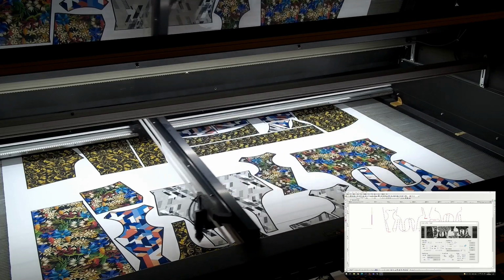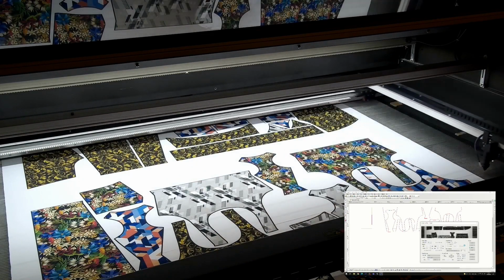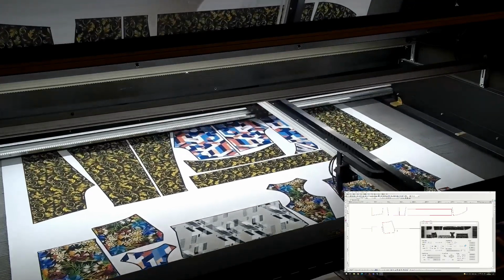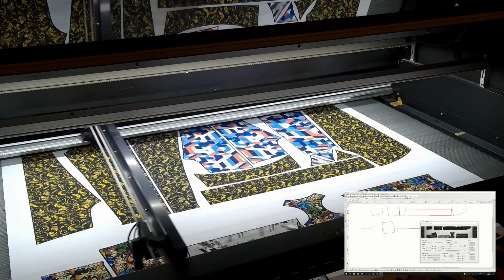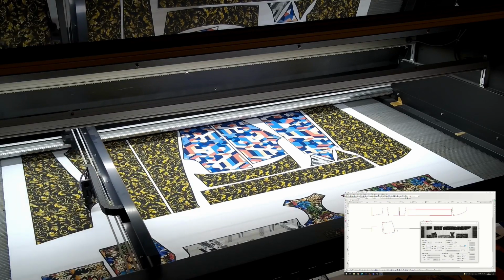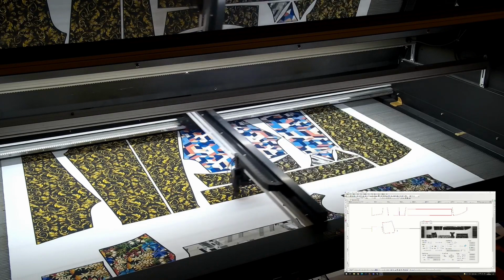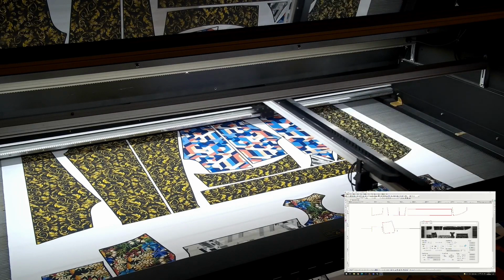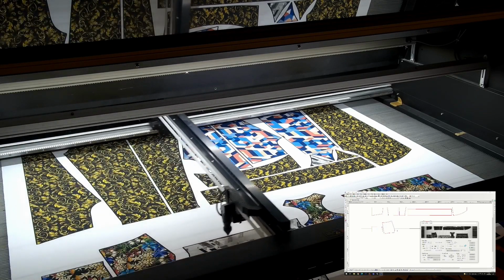Here you can see the waste cut, and the waste cut is generated from right to left or left to right. It will do this related to the last cut, and it will only cut the waste. It will not cut through your design, of course. It will start outside of your material, go to your first object that was cut, and then skip that, because with the laser you can easily switch on and switch off your laser beam, and that's going to be a very big advantage for your speed. Here again, it's going all the way, and it's linking up all these shapes.